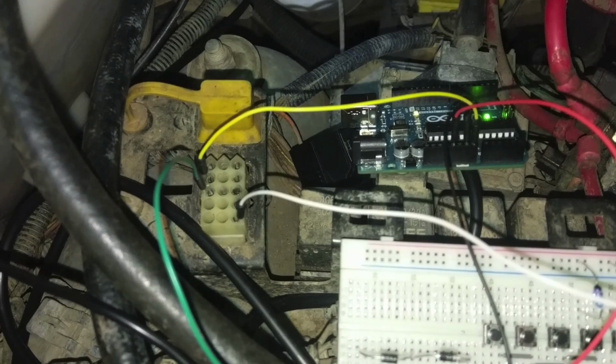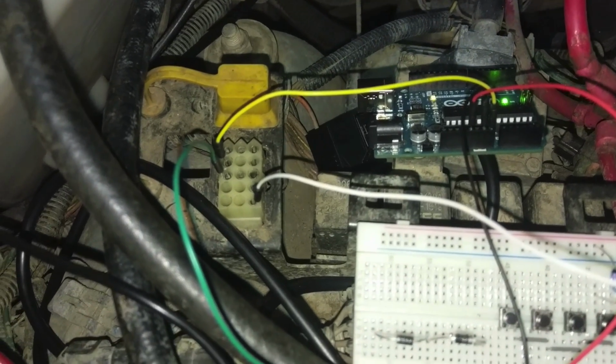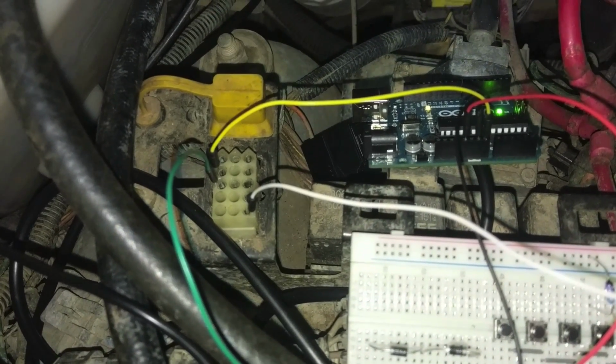But if I take that black and go to positive, we get a full tone. If I went to TX to ground in a certain position, it seemed like I got some decent data. So now the negative is going to go to the TX, and our positive is going to go to ground. That gets us the signal we want.